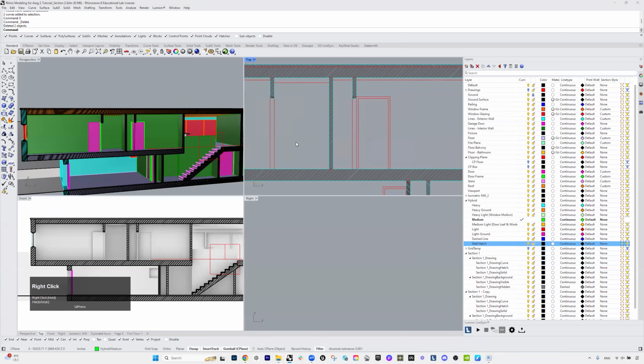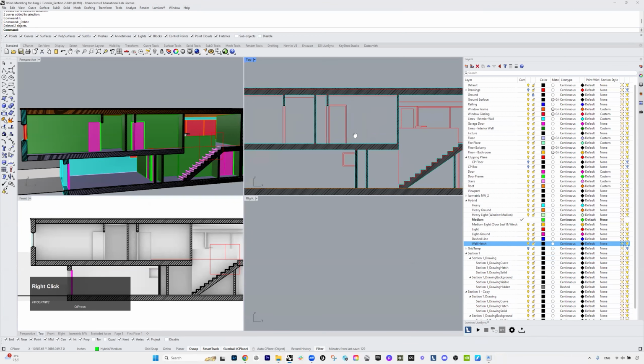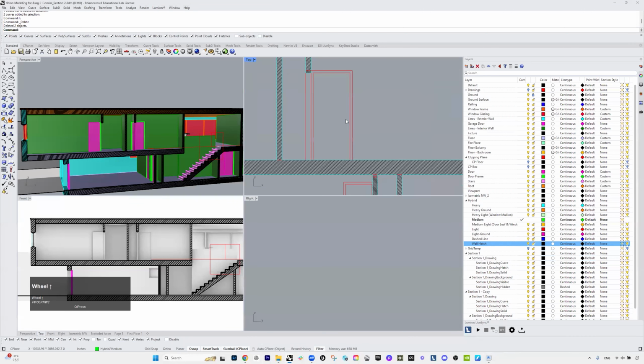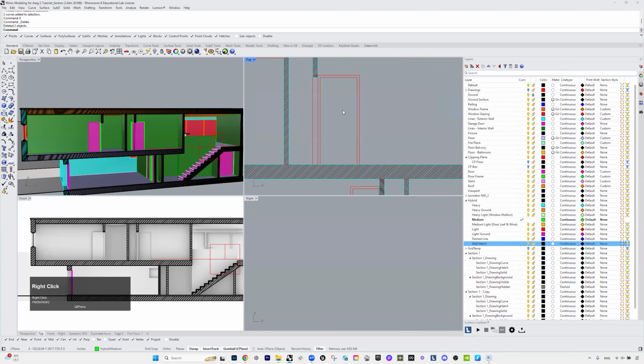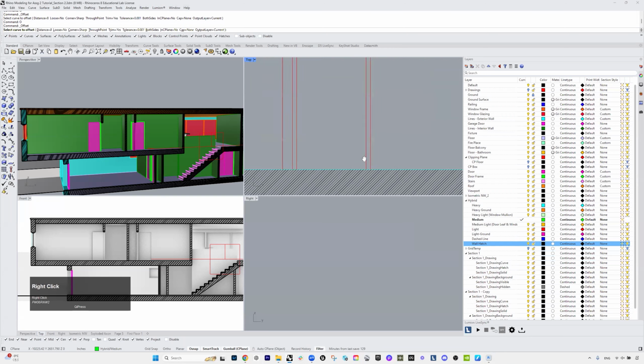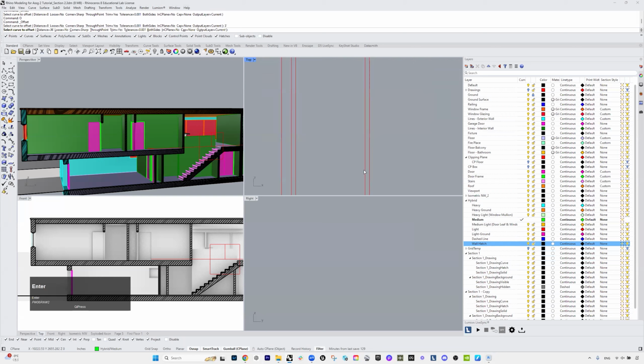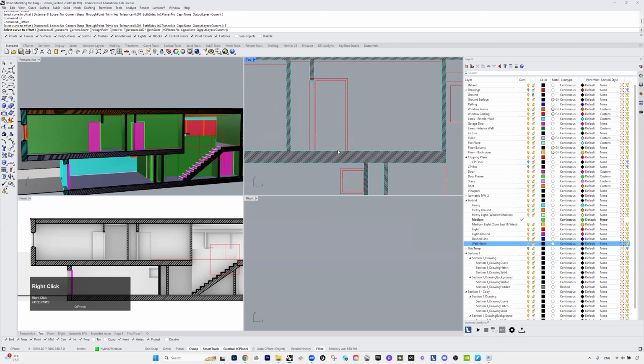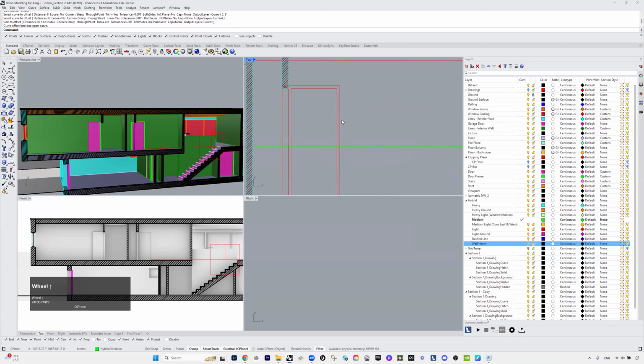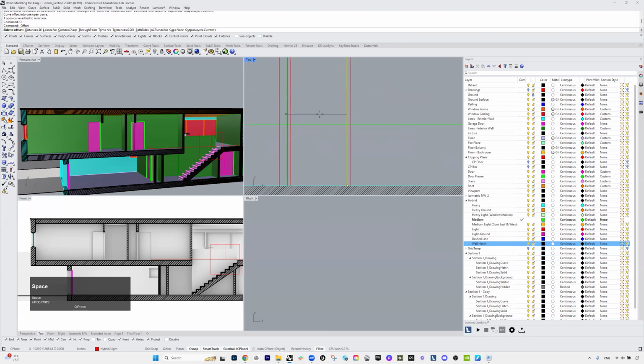But in this assignment, I don't really want to do that. I thought I'm just going to draw a doorknob over here. To do that, I'm going to offset this line that's representing the floor by 3 feet. Let's see, I select this line, move it up, and offset this line over here by 2.5 inches.